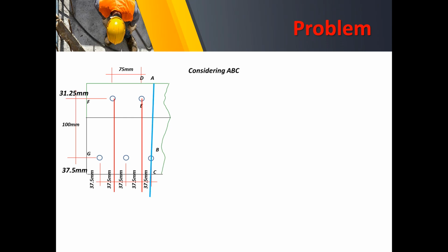So the second unknown, of course, we need to consider the net area or the net width. We are concerned with the least net width we can calculate from this staggered connection. Primarily we consider the first row, considering ABC. So the net width on ABC is 168.75, which is actually the sum of these three.